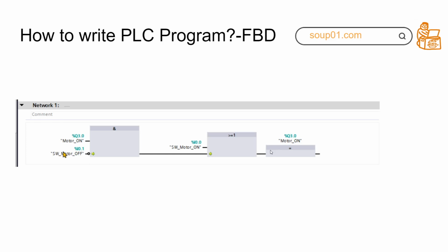For some plant projects or simulation, depending on the end user, they may request you to use FBD because it's easy to read. But you will not prefer to program very complex logic in one network, because it makes your program not easy to read.